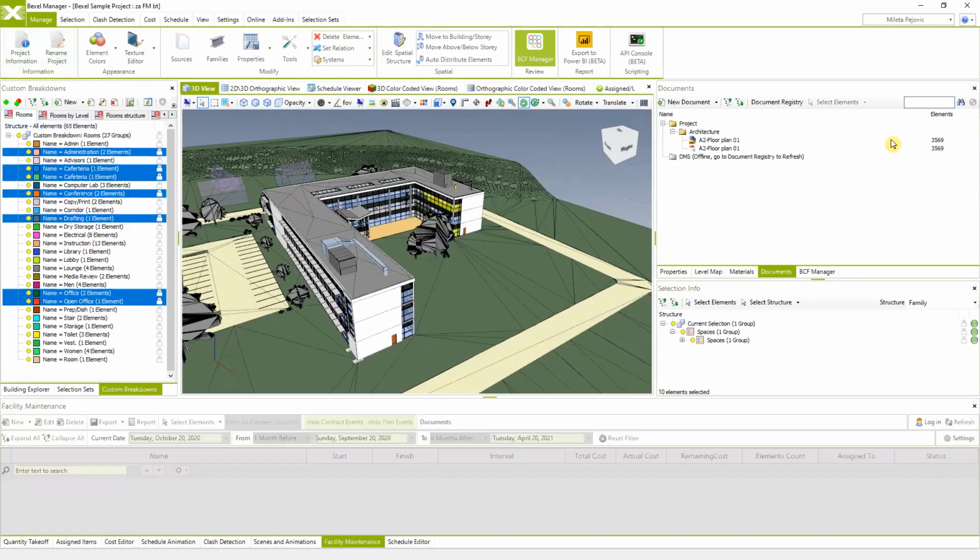Another really important and great feature is that when you're linking these documents to the project, you can also choose to relate the document to the BIM model itself, to specific elements of the project, of the building, or to specific assets of your project. In that case, you're making a specific relation between linked documents and your selected BIM model elements.